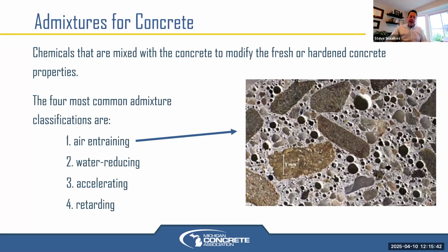So any percent above that range, typically, or above what we designed for, every additional percent of air reduces the strength, because there's no strength in air. There's strength in cement and aggregates and everything else. So if we're putting more air into that same volume of material, it reduces the strength approximately 8% for every 1% above the range. So yes, it'll start lowering the strength, but typically strengths are generally not an issue for most pavements and even for most structures.